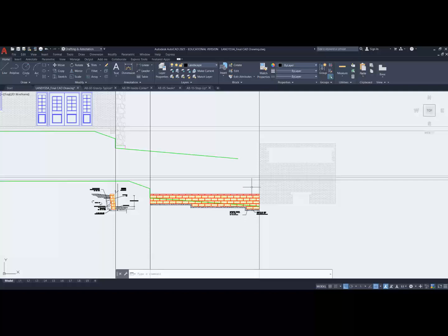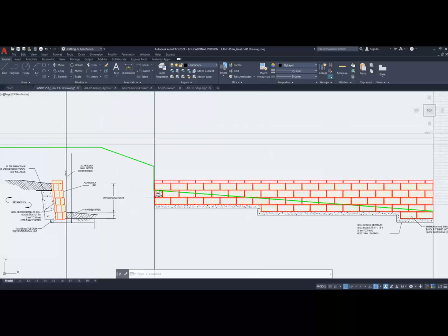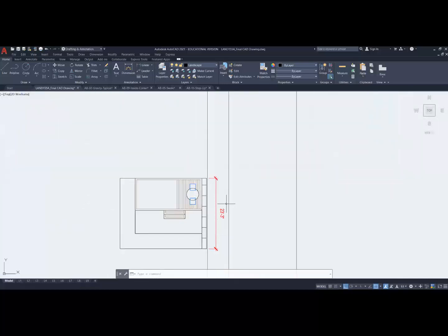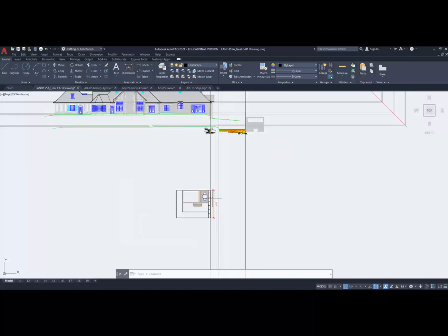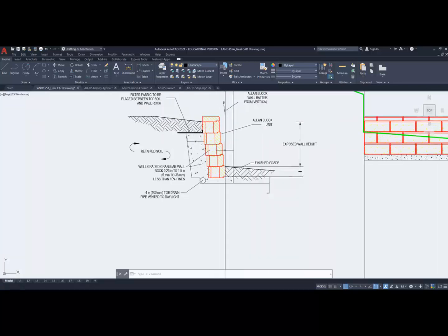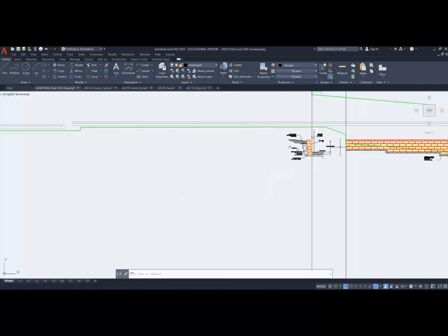So when I'm going to draw my section line here in the different views, that's where that sectional line is going to be. My end view is only that height. It's much smaller. So this is my top view, and that's not going to need to be corrected. There's a couple of elements here that I need to add. There's my top view. There's my sectional view. There's my right side view. The only thing I don't have is my end view. My end view is this, but to that grade height that I have here.